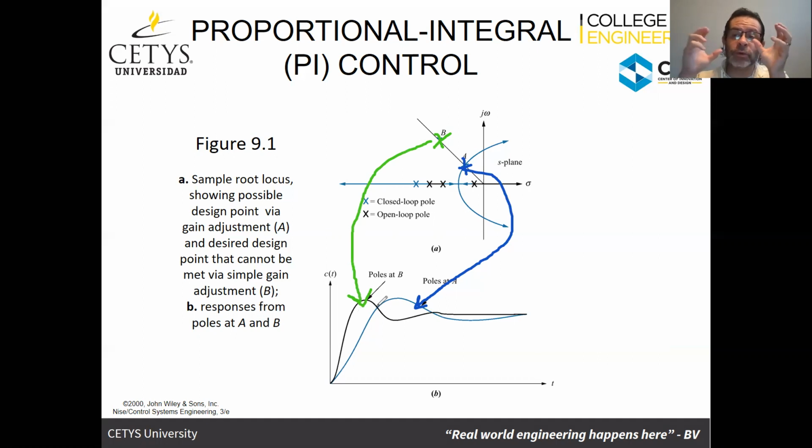So what I'm actually doing, remember, when I'm adding the controller, is reconfiguring the root locus to have other alternatives for poles and zeros that comply with the system and therefore can have different behavior. In the end, remember that changing the poles of the system, or the reconfiguration of the root locus, is going to provide me these different behaviors.